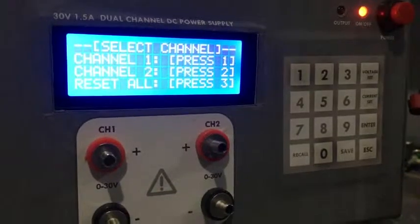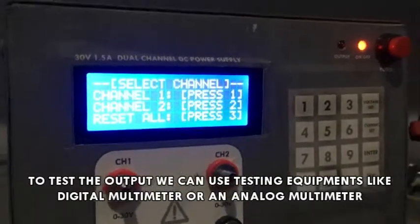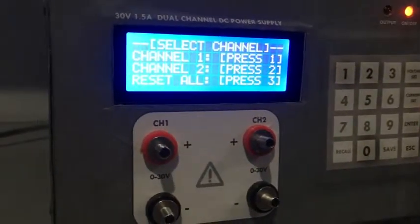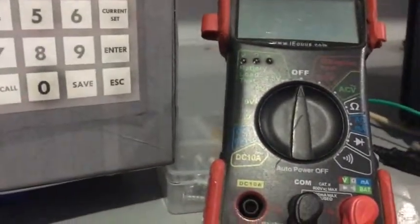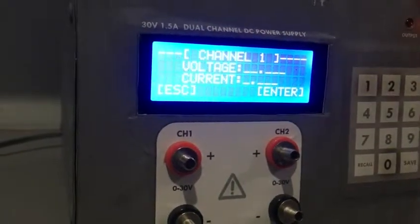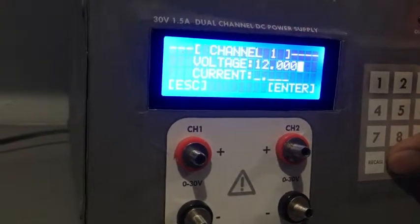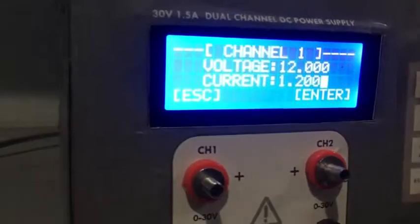Testing the output. To test the output, we can use different testing equipment like a digital multimeter and an analog multimeter. In this case, I will use a digital multimeter for convenient reading. First, I will set the voltage for channel 1. I would like to set the voltage to 12 volts, the current to 1.2 amperes. I'll press enter.